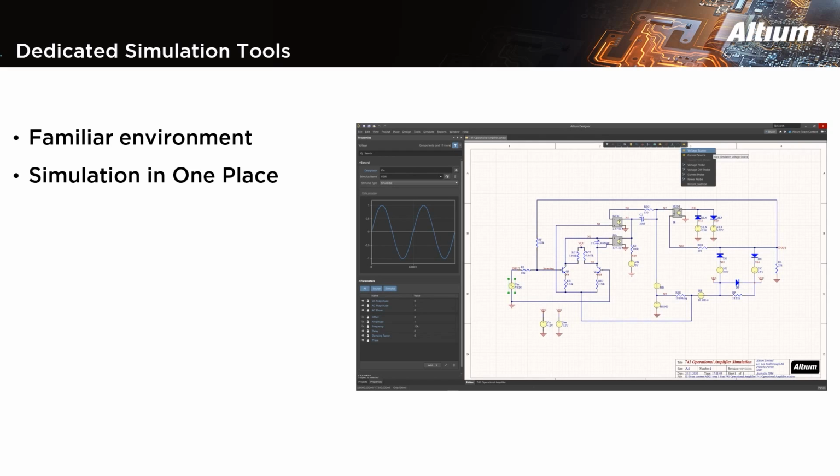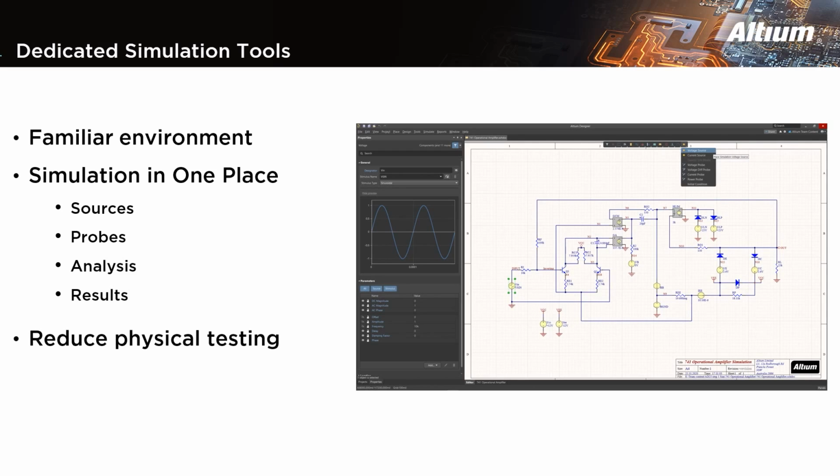One of the biggest changes is the new simulation stimulus source interface for voltage and current sources. In addition, there is an area for probe definition. Each probe has its own properties to show the associated net name, simulation results preview, and the ability to set trace color. The quick simulation cycle ensures your schematic and selected components work according to specifications.